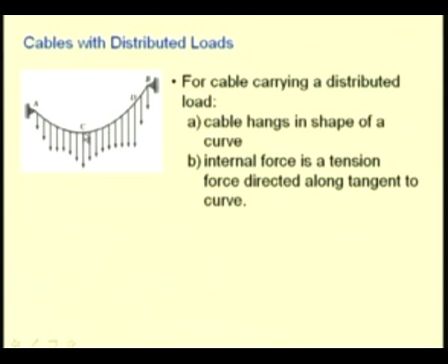Let us say at C, where the tangent of this curve is horizontal, the tension in the cable is directed in the horizontal direction, and at B, where it is fixed, the direction of the tensile force is tangent at this point, and which is also equal to the reaction at this point B.